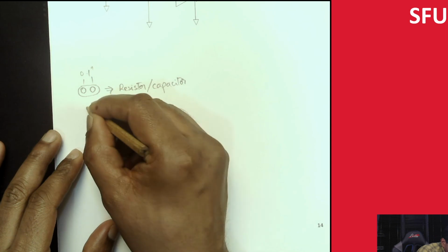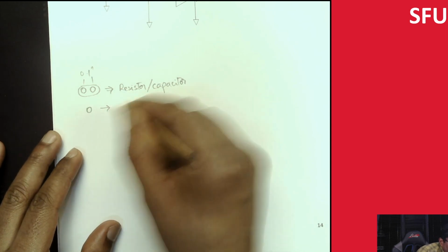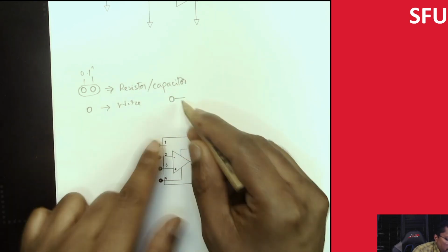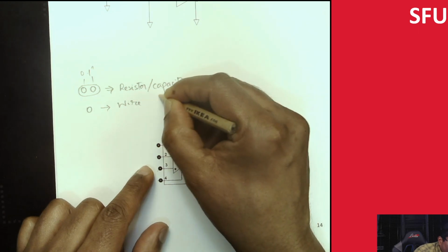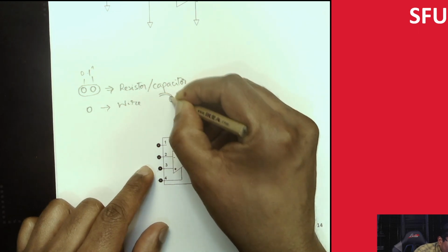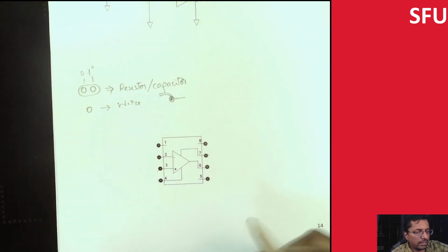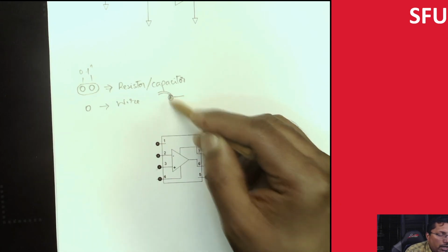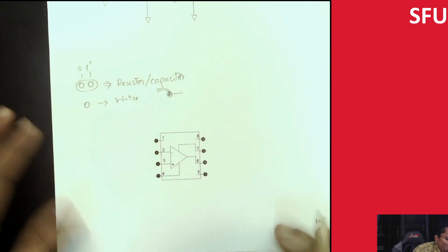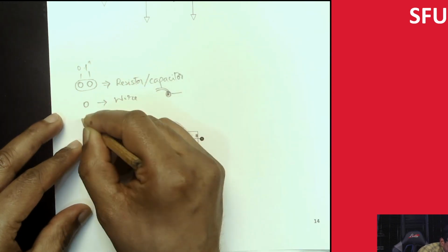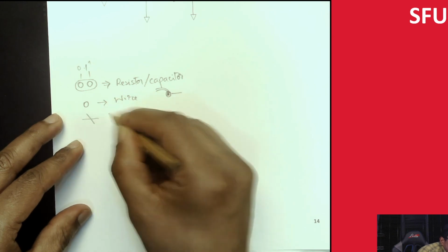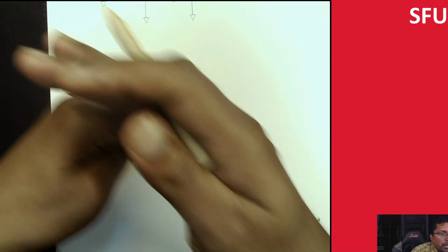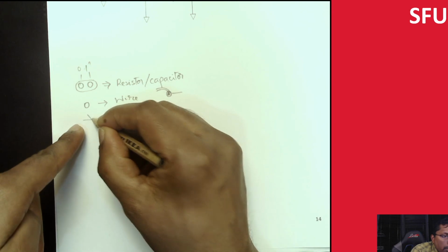If you have a single line like this, this is going to be a wire. If you have a wire, then you're going to have a trace, and this might be connected to one of the components over here. Then you might get a wire from the outside, solder it over here, so this is a physical wire coming from outside and soldered here. So in our circuit board, we're just going to have a pad or a wire pad over here. The other thing to note is we want to make sure that your traces never cross each other. So this is actually wrong, because if you were laying this out in a circuit and they cross, there's going to be a short circuit created over here.